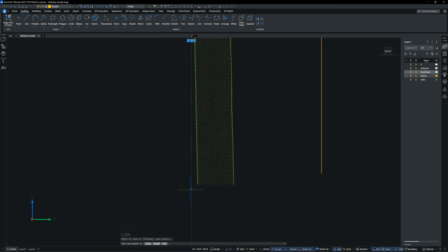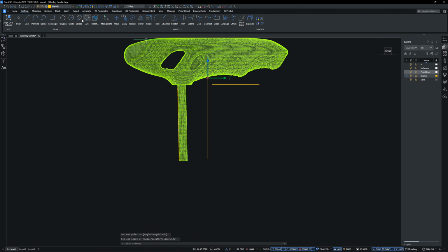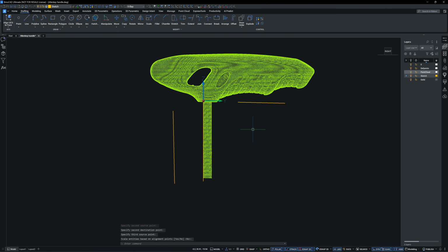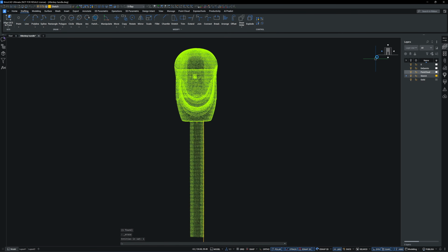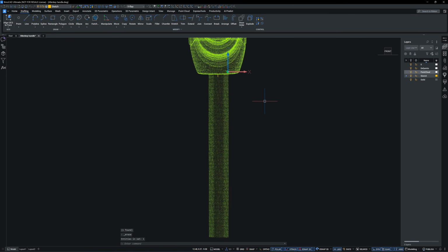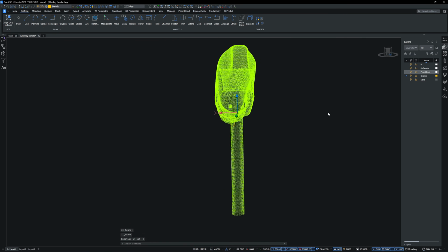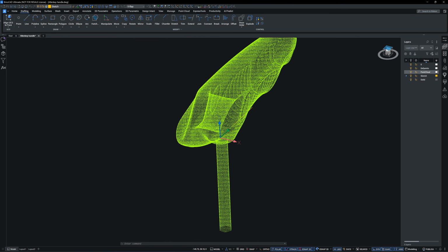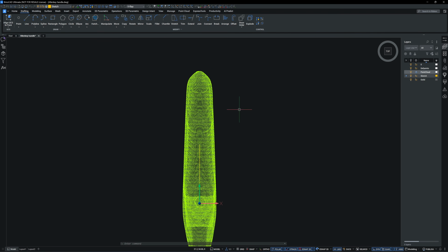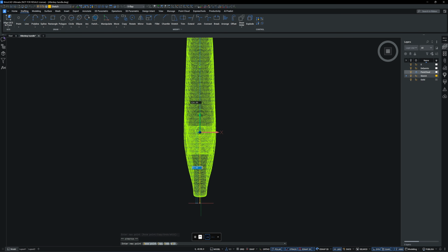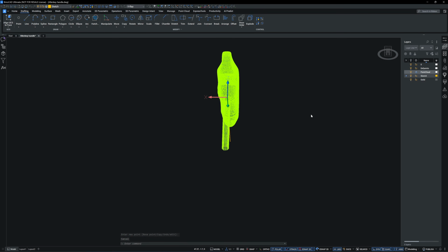Now the point cloud is perfectly aligned to the mirror axis, and the hex key is oriented to the vertical axis across all planes. Finally, I move the point cloud together with the center line to the origin where the XYZ coordinates are set to 0.